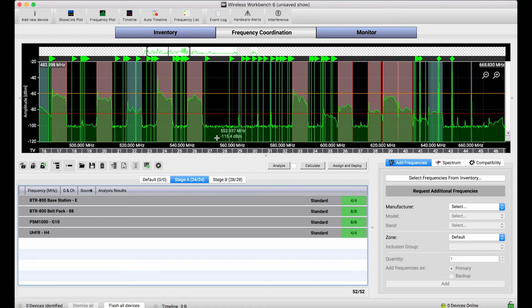Now you might ask, well, how far do these locations, these zones, need to be apart from one another to consider them zones? It's less really about physical distance and more about RF propagation. In general, we recommend at least 300 feet between the locations, but it could be more if you've got a wide open space where RF can propagate really well, and it could be less if there are metal walls or other obstructions that would limit the propagation of RF between zones.